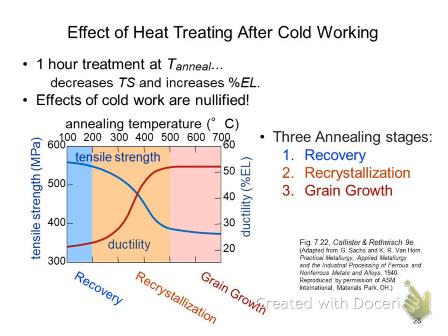We've already talked about tensile stress. This tensile strength I'm using as a stand-in, maybe ultimate stress, for that particular strength. If we start here with a material that we've cold worked, so it's after cold working, and we have a very high tensile strength, and then we choose to hold it at some temperature that we're going to call annealing temperature, and let's use 1 hour as our time. What happens is it follows this blue path here.